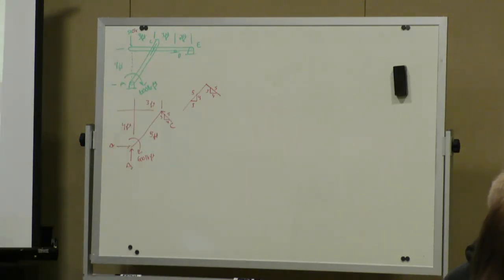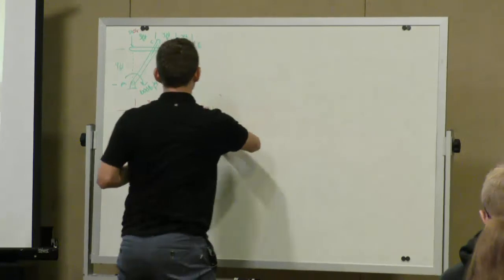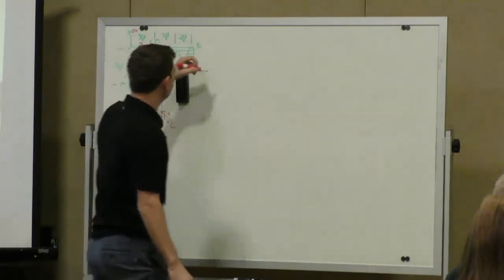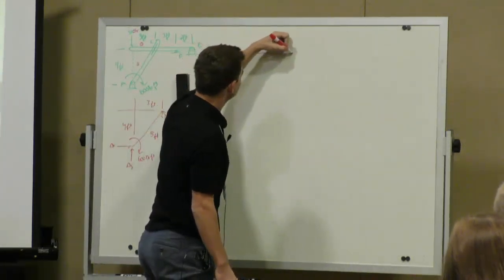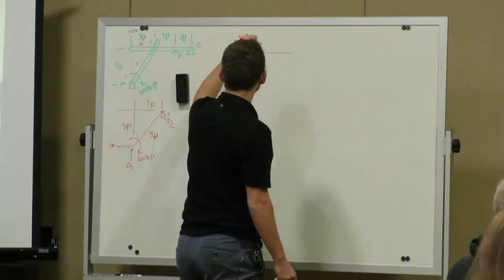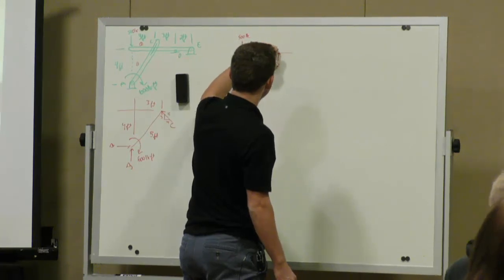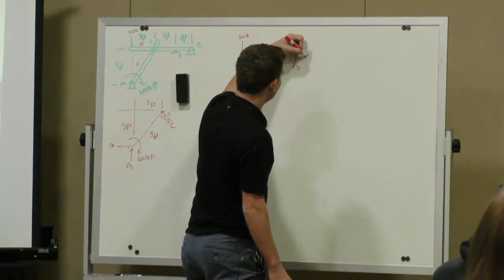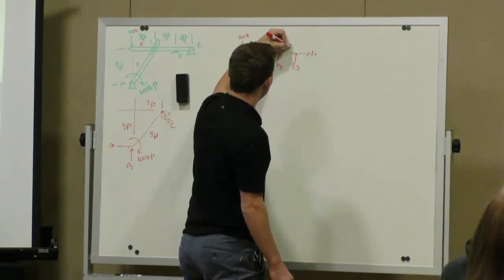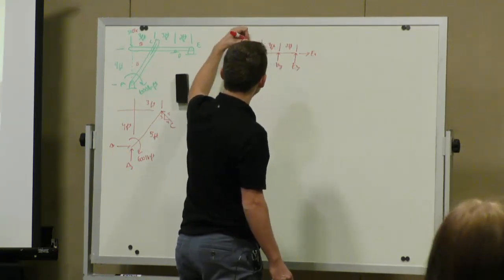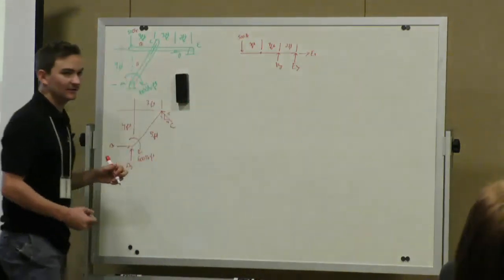All right, so now how do we solve for those reactions? Can we solve for it, or do we need to draw the second free body diagram? So that's of member 1, this is member 2. This is 500 pounds. This is C. So we determined D has only a Y, and E has a Y and an X. This is 2 feet in between. This is 3 feet and 3 feet. So what is the support reaction going to look like on member 2?